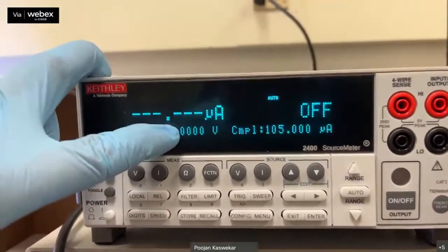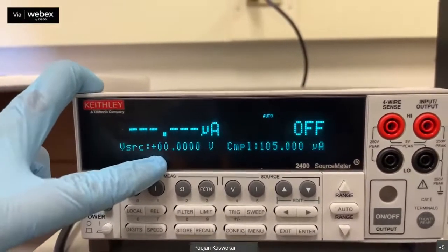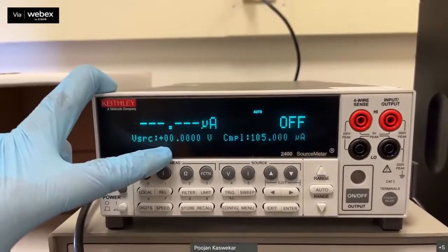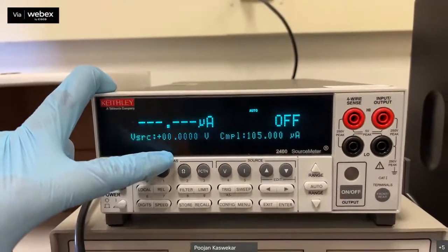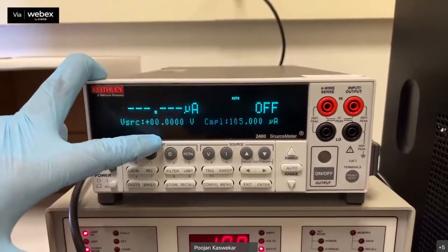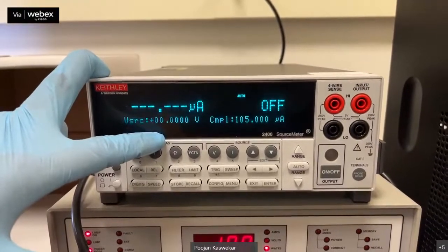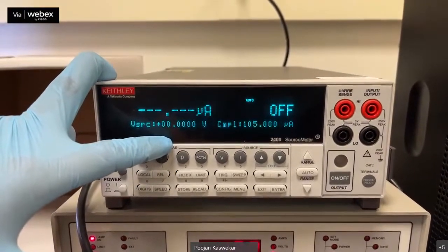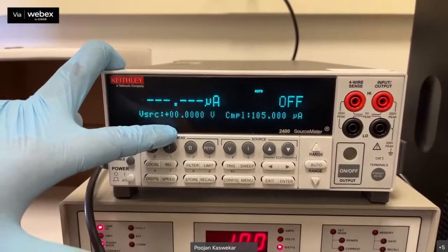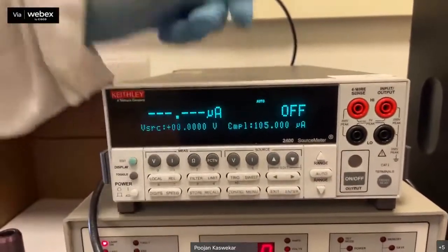Typically for a solar cell, we expect the ideal VOC to be close to the band gap of the solar cell. Suppose your band gap is 1.51 electron volts, theoretically your VOC should be plus or minus 0.2 of that, that is 1.31 volts. But the recombination, the shunt resistance, and the layer-to-layer recombination cause a lot of VOC loss in our sample. So for a typical sample of MAPbI3, we will get 0.9 to 1.1 volts.